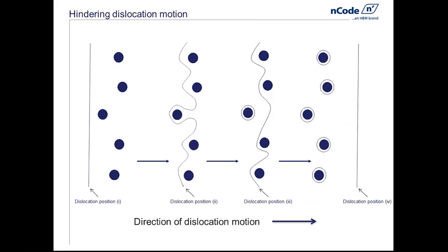Here is a demonstration of how dispersion strengthening hardens up the material. If you look at the extreme left, I've got an imaginary dislocation as a straight line that I'm wanting to move across those particles, which are the spherical or circular lumps in the material. So I'm pushing on the metal, and the line of the dislocation starts taking a convoluted appearance as it tries to form around those particles.